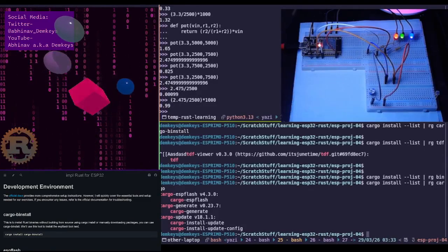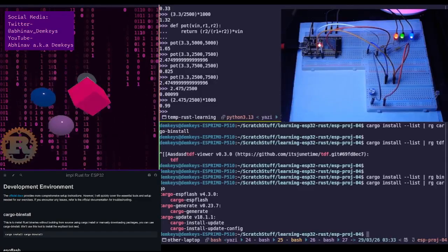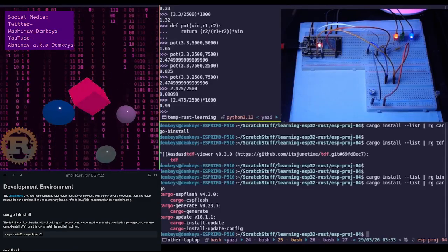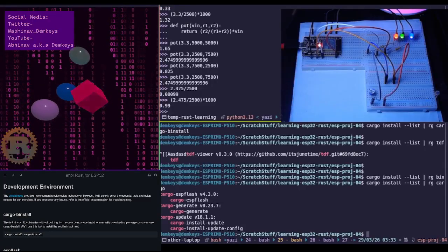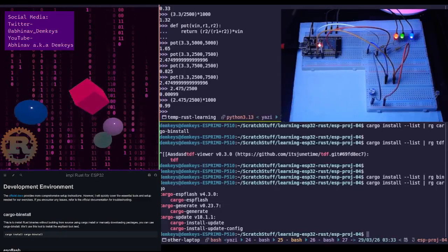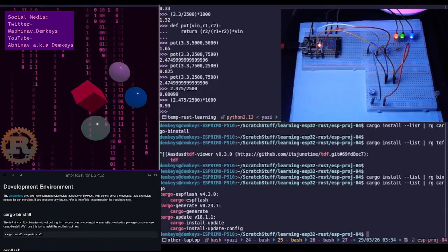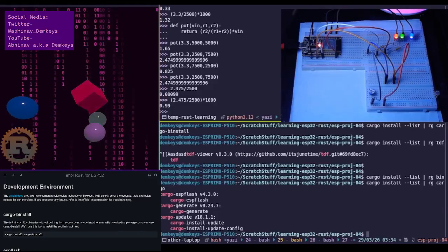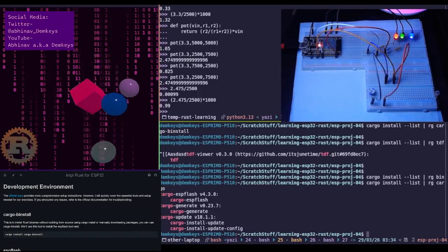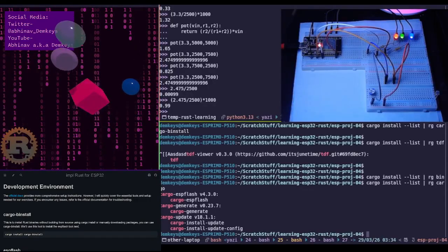But yeah, I've been doing a good bit of research, and this has taught me that before I just rush to buy one of these things, I should absolutely do all the research that I can, not just about the hardware, but also about being able to program the hardware, because I had no idea that you absolutely need a separate flashing device in order to flash the binary onto the CH32V003.